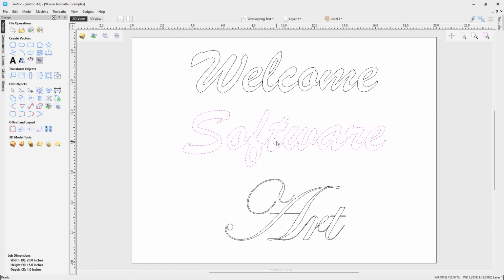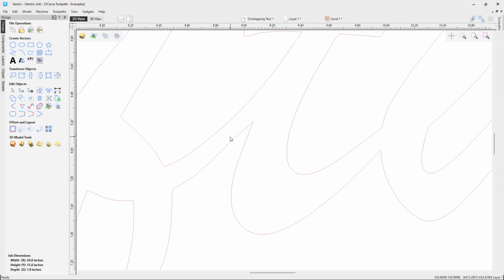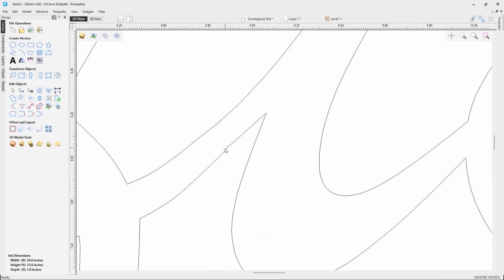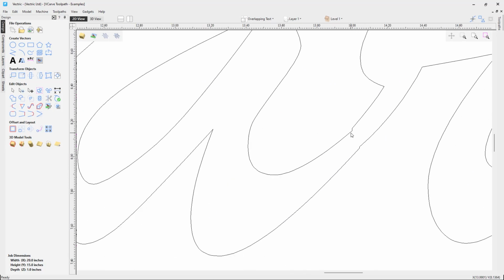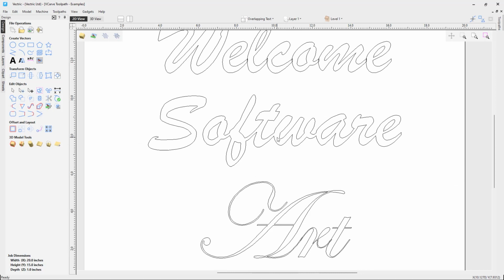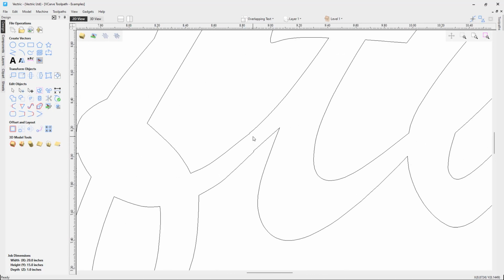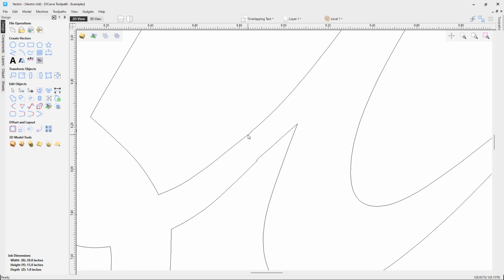And then we'll zoom in on those trouble areas that we saw. And again, you're going to see that there's a little bit of a step there, which we kind of expected. And over here, there's a step as well. Now you can go ahead and run your VCarving on that, and it's going to remove that little wall that you have, but there'll be a little bit of a jog in the side of that. So let's go ahead and fix that.